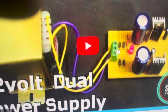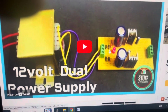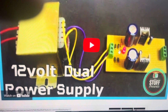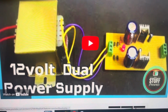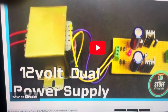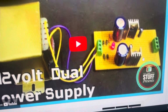So from here, this one goes to the diode, and from the diode it is converted into what you can say is pulsating DC. From here, the system will go to capacitors. Now from the capacitor, it becomes a perfect DC, a filtration capacitor, perfect DC, and from here it will be fed to the voltage regulators, and at the end we will get the specific voltages.